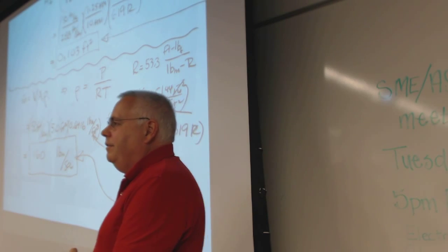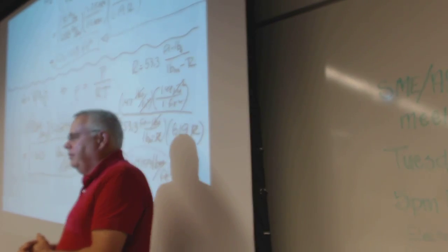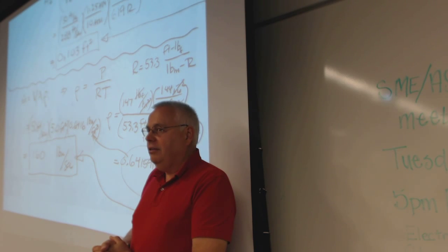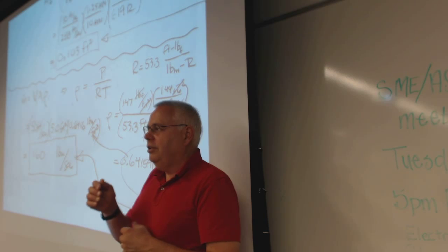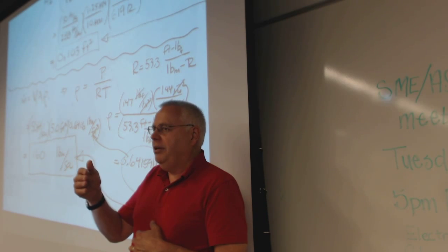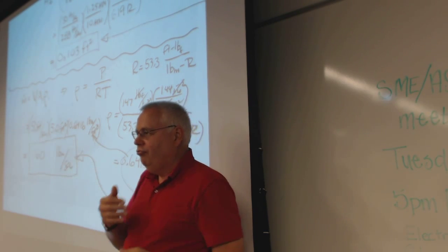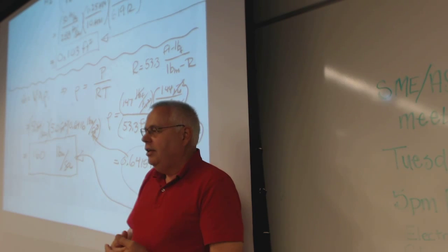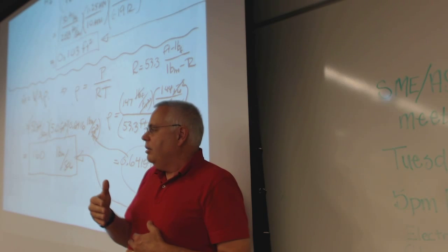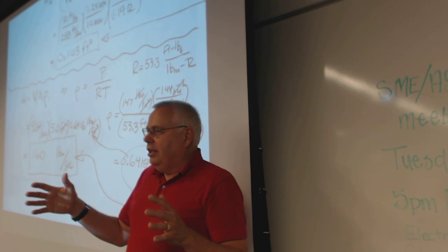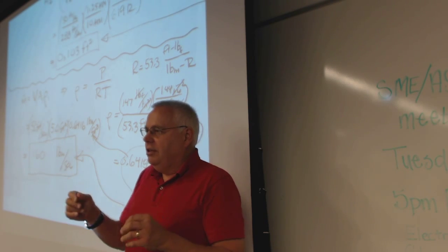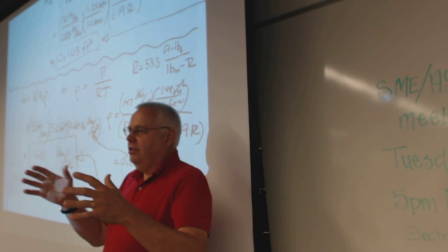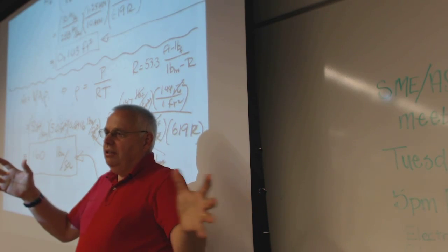if you start going fast enough that you get into supersonic flow or approaching sonic speed, the speed of sound. Speed of sound is really the rate at which energy can propagate through the molecules of the air. It changes with temperature because the temperature changes the density, etc. And when you get close to that speed, you'll actually get a shock wave.